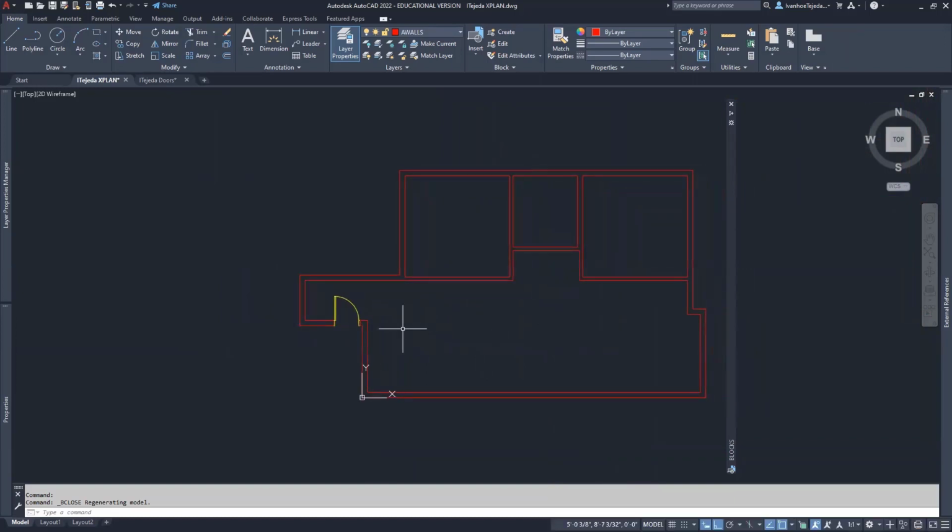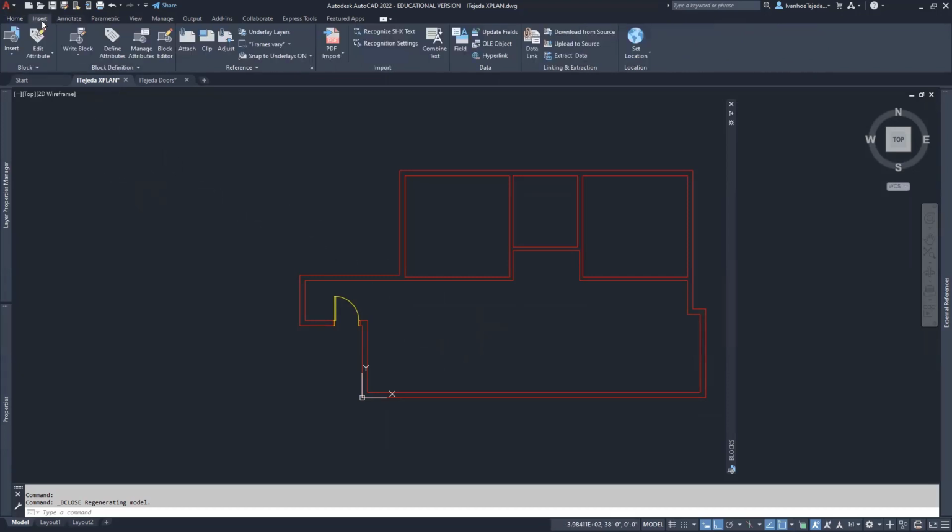And then let me show you, I'm going to get ahead of myself for a moment. You're going to be bringing furniture in as blocks, but there's no need for you to always make individual blocks. You can if you want to, but watch this. To bring in the furniture, if I go back to insert, actually I already have it open.